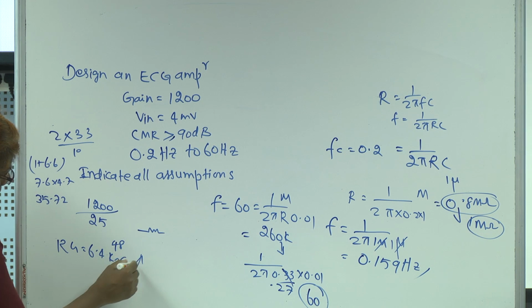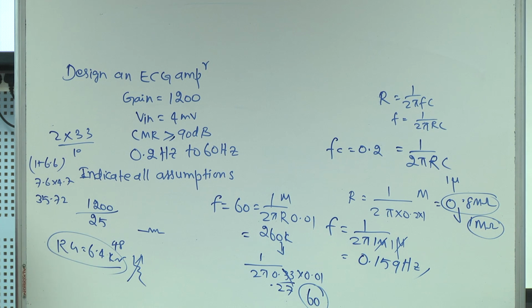I use a pot. So if you use RG 6.4, what happens? You get 37, I guess. So then I use 47 here and 37 here. Anyway, you can play with this. Yeah, everywhere I use that one. I use 330K, 0.01 microfarad, 10K, 1 megohm, 1 megohm, 1 microfarad, 47K, 10K, 47K, 10K, 22K, 6.4K, 22K.